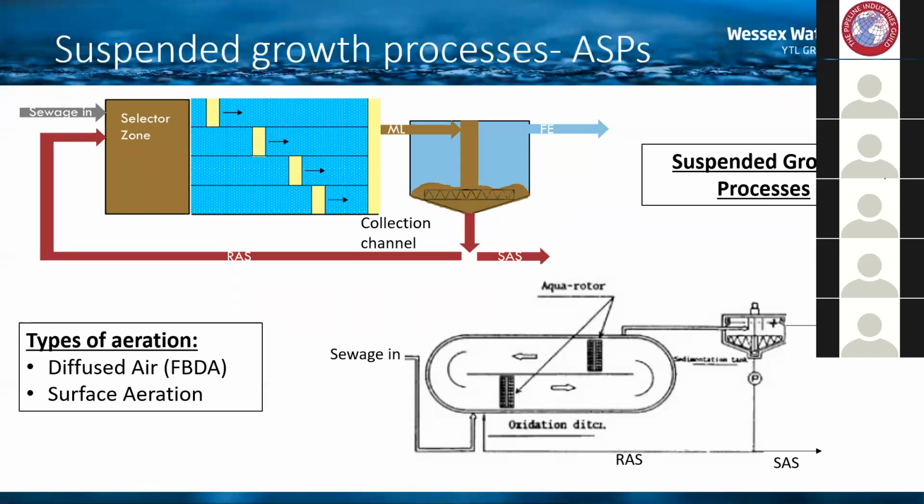depending on the site setup. The bacteria that are collected at the bottom of the tank, in this process, can actually be reused. So they're returned back to the head of the process, and that's our RAS, our return activated sludge. It's being returned to the head of the process to be mixed with more incoming sewage and go through the entire process again.